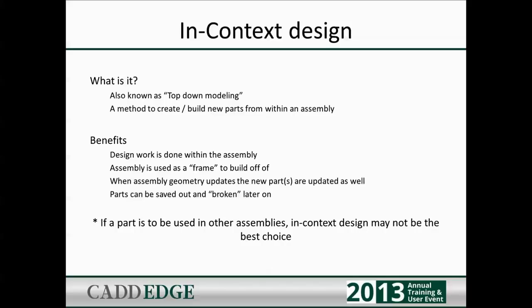That would be bottom-up assembly modeling. Top-down modeling is the exact opposite of that, where I have a frame and I want to build parts to fit within that frame. Using that frame as a guide helps me design around my parts. So that would be top-down modeling.